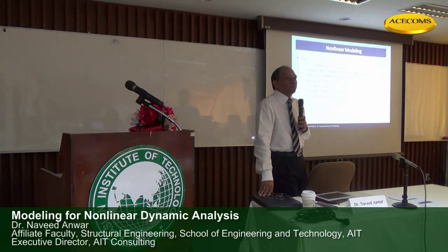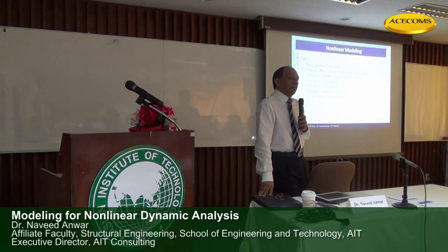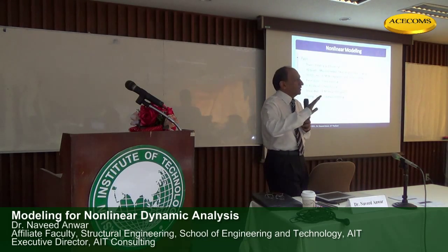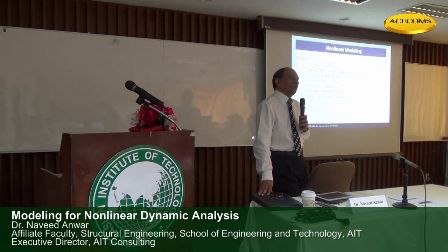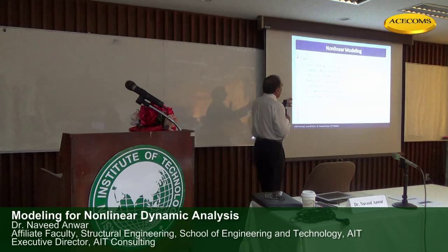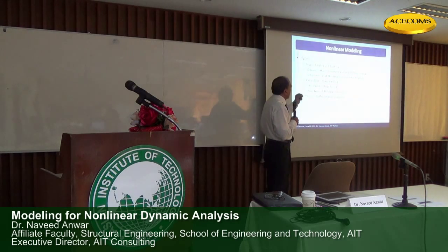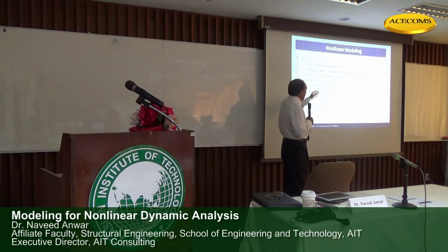So some engineers may consider modeling that nonlinearity also. Some engineers say, no, I don't want to bother with that. I will consider shear to be brittle, and I will not model it as a nonlinear component. So there is a level of judgment involved there. Column: PMM interaction and shear hinging. Panel zone: shear yielding. Infill panel: shear failure.